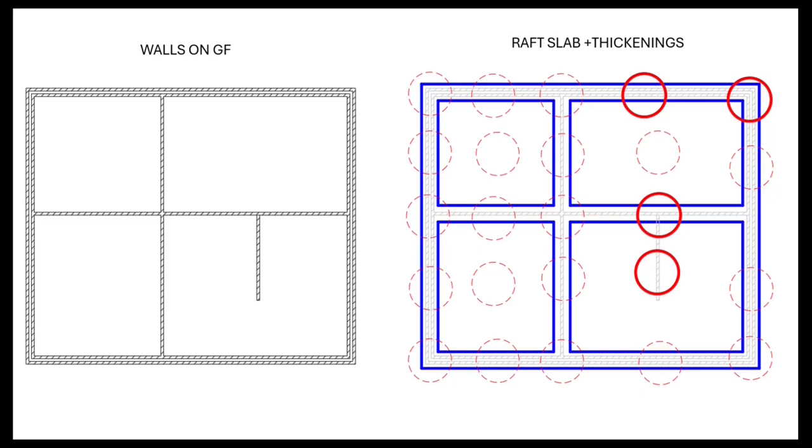And as I mentioned before, in case of semi-flexible rafts, we are not checking the raft as one whole element. Instead, we are checking local smaller parts of rafts. So on the right side, I showed them with circles: continuous and hidden line circles.